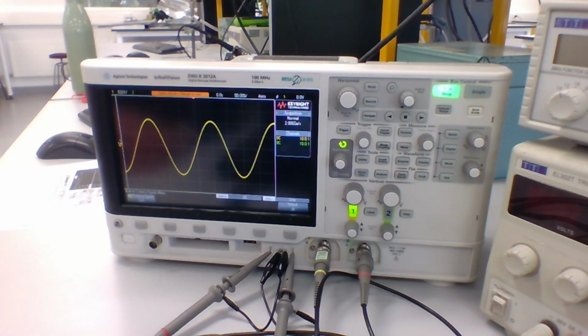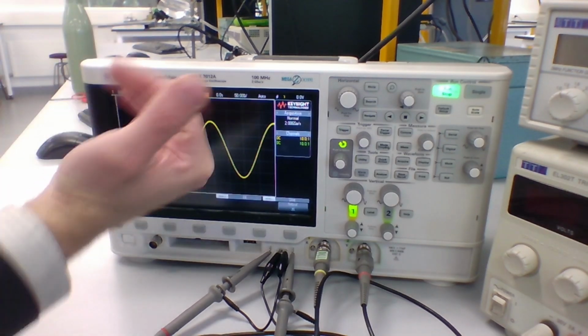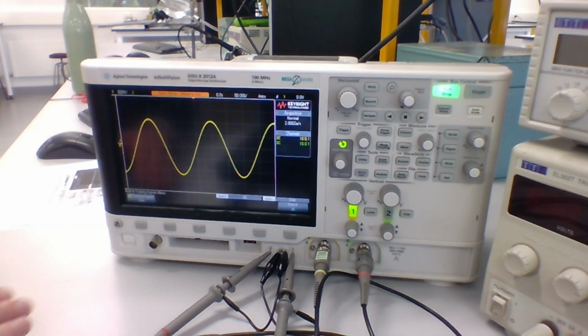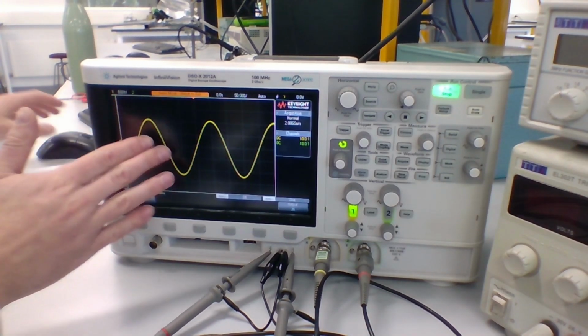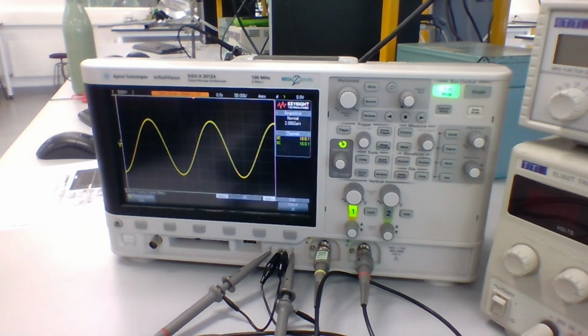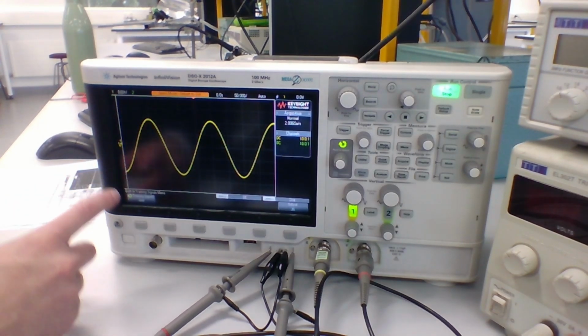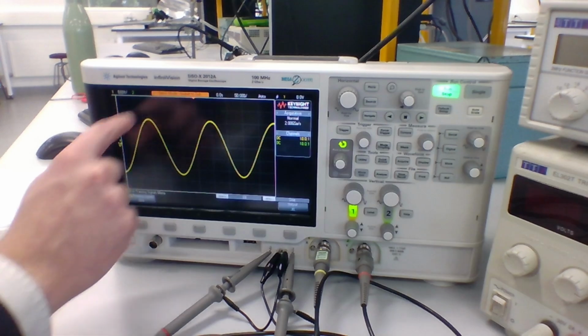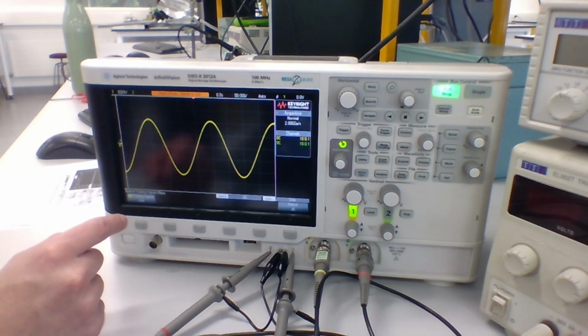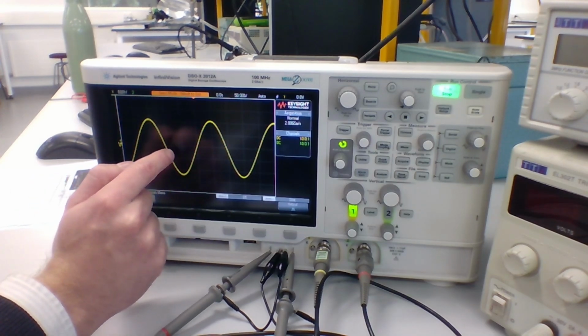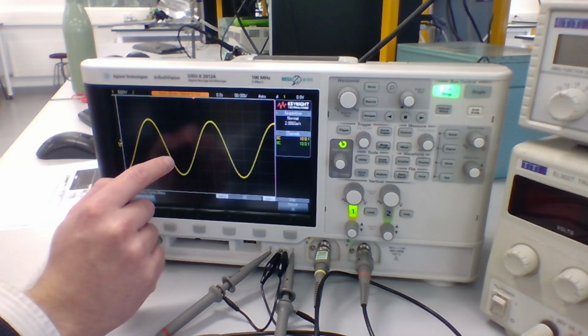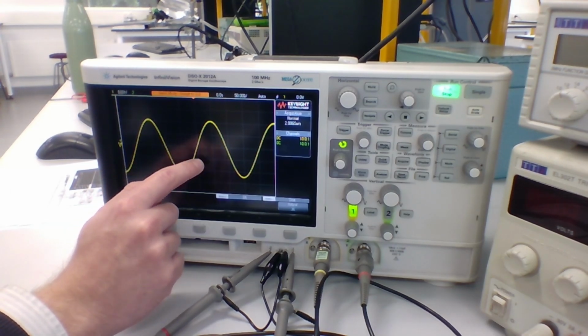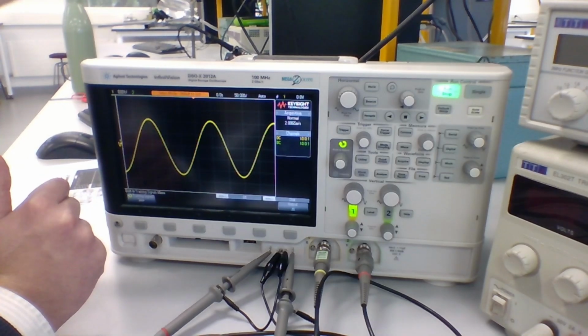Okay. So now we know how to scale this oscilloscope vertically and horizontally and how to move signals around on the screen vertically and horizontally. The next thing we can do is start taking measurements from the oscilloscope. And again, there are a few different ways of doing this. Following the guide manual here, the first thing we can do is estimate using the marks on the screen, this grid line shown. We can see there are these major grid lines, and if you look closely on the oscilloscope, you can see there are smaller subdivision ticks as well. And we can use those to actually make measurements.